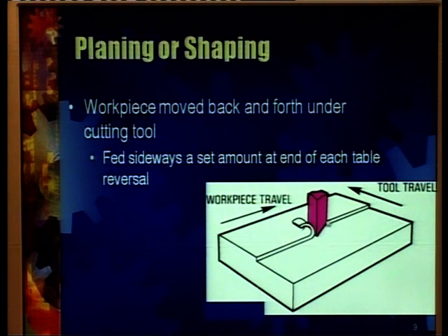since the depth of this cut is such that if we move the tool further in the same direction there will be no material to be cut in the path of the tool, and so as to do machining on the whole surface, we set the machine in such a manner that after this cycle is completed and the tool has been moved to this position, when the tool returns it moves in this direction a bit, so that now it is at this position and is removing the material to the side of the material which has already been removed.